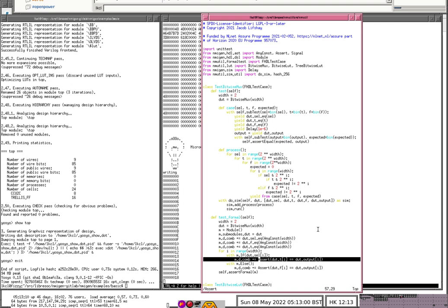You can get the formal correctness proof wrong, you can put in the asserts and assumes wrong, but the point is that the engines, which are very similar to functional programming languages, try very, very hard to find some combination of inputs and outputs that is guaranteed to be wrong, and then show you what they are. If it can't find any, then you're good to go. So it's very, very cool.